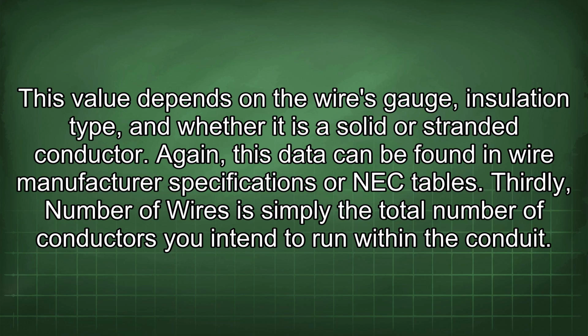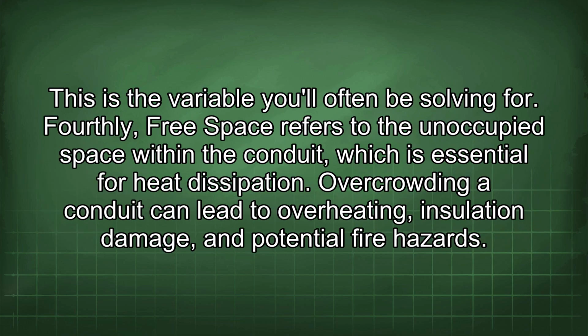Thirdly, number of wires is simply the total number of conductors you intend to run within the conduit. This is the variable you'll often be solving for. Fourthly, free space refers to the unoccupied space within the conduit, which is essential for heat dissipation. Overcrowding a conduit can lead to overheating, insulation damage, and potential fire hazards.